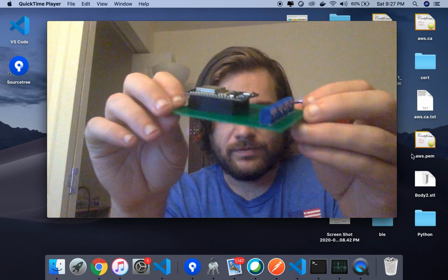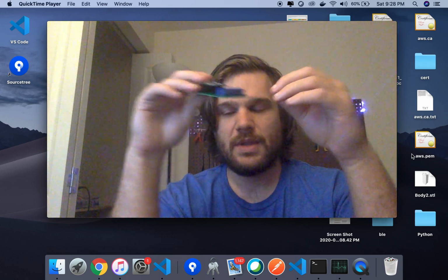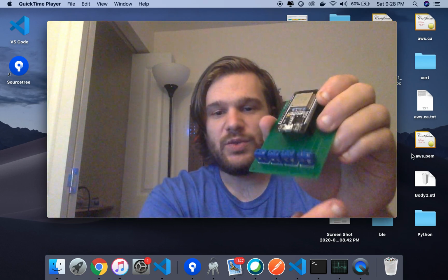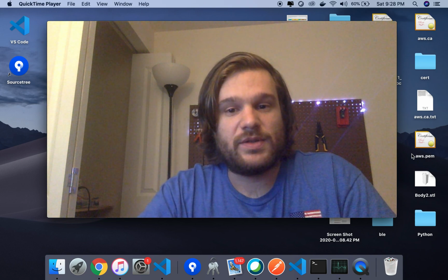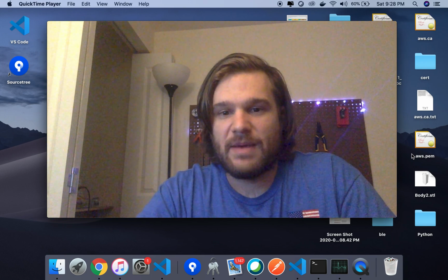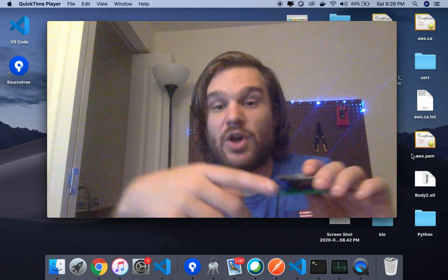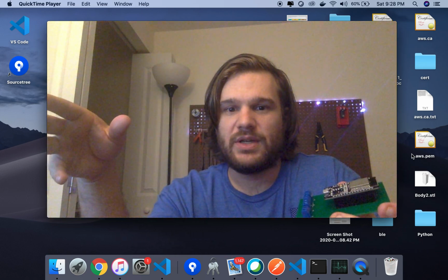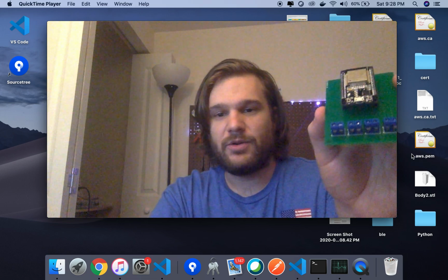The first thing I noticed with this board is a concept called floating pins with Arduinos. Each of these terminal blocks has a ground and a digital pin, and digital pins have two values: high or low. High is when VCC goes to that pin, and low is when ground goes to that pin. But in the floating pin situation, when it's open, it's an open circuit, so it could read as a 0 or low, but you're not actually reading the ground value, and it's indeterminate. So one thing I need to do is fix the floating pin.